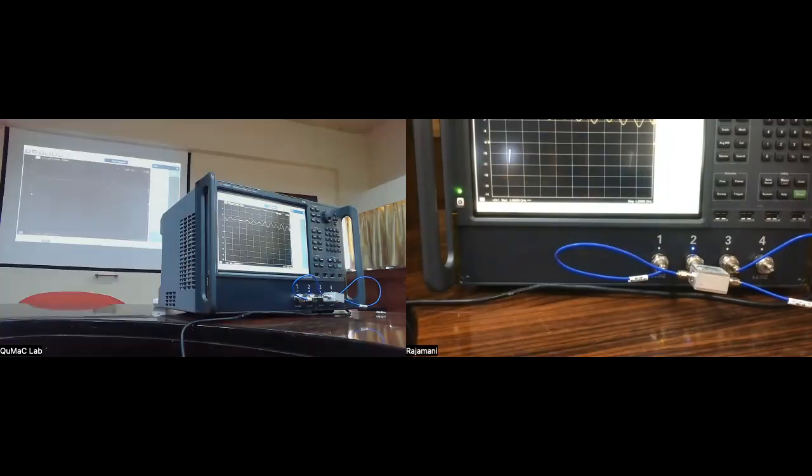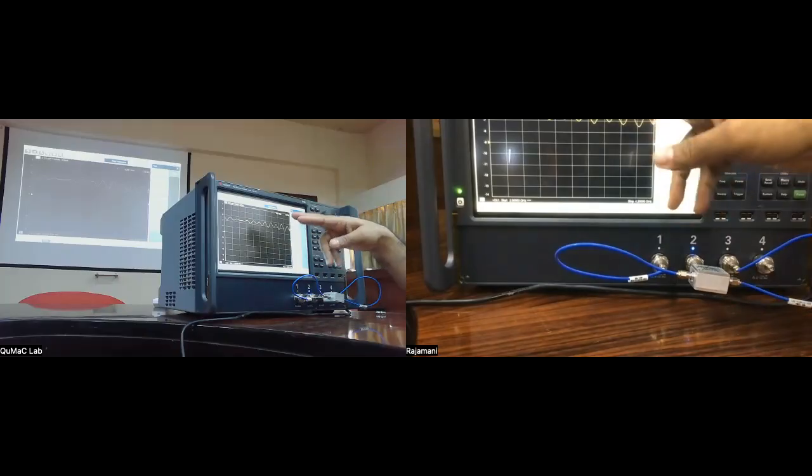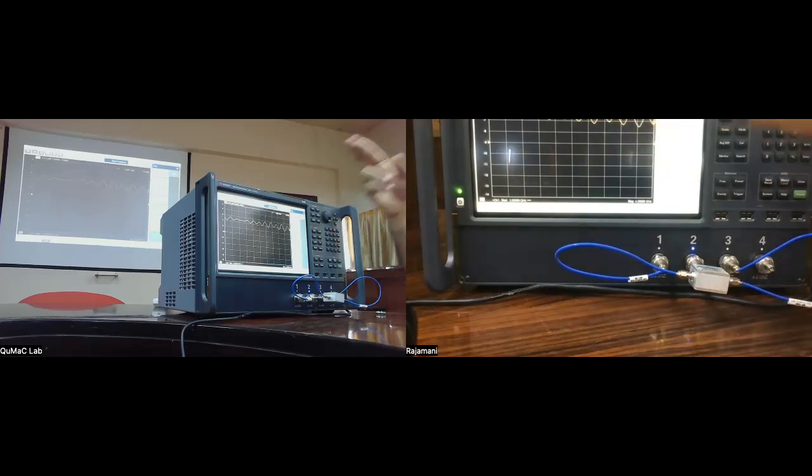The previous one, the Wilkinson divider type model, does not have a resistor except for that difference port, which in the ideal case should not even be dissipating any power. Here, because it is using resistors, it's a network which cannot be defined as lossless, right? It's made out of resistors, which is a lossy element. So this is not a lossless network, and it will always have this feature that the output power is going to be 6 dB on both ends, which means it's a factor of 4 in power, and half of the power is lost. So 1/4 goes to one port, 1/4 to the other.